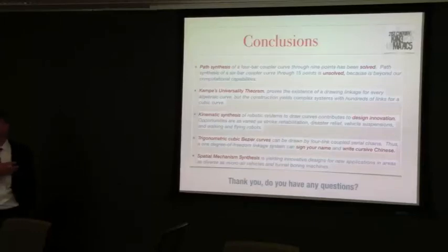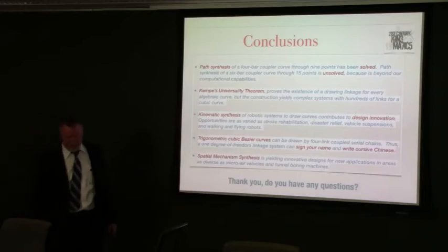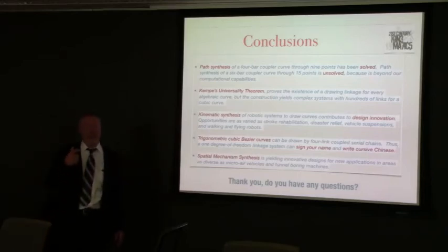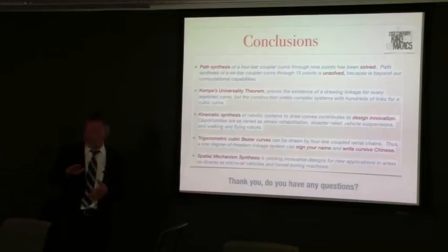And that goes for all of our devices, frankly. We impose the requirement that our links be a fixed length, but what we've discovered is that you want to have some sort of adjustment. For example, we've been designing knee braces that track a particular trajectory, and we got very close to that trajectory, but we had one point that was kind of off. There's kind of a lobe that was misplaced. And rather than redesign the whole thing, we asked whether there are any changes we can make to this particular device to bring that lobe down.